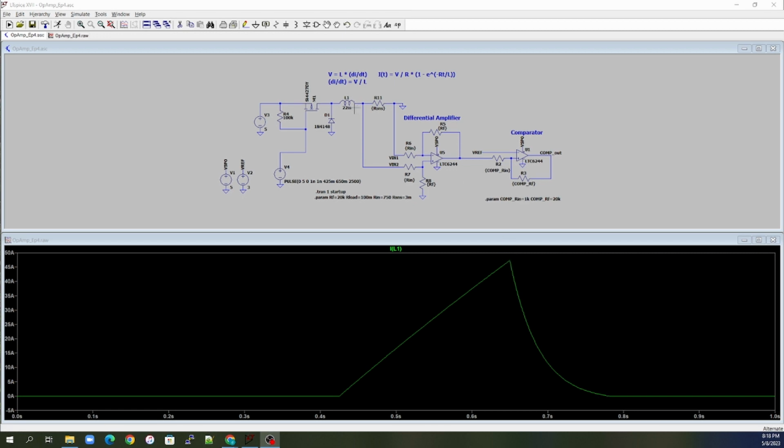So we could control current through this inductor. Let's say we want to have 50 amps. Then what we would want to do is try to keep this at 50, because we know that if we just have this switch on, our current will ramp up to 1600 amps, but we want this thing to hover at around 50 amps. So we need to be able to turn it on at 50 amps, but then what do we want to do?